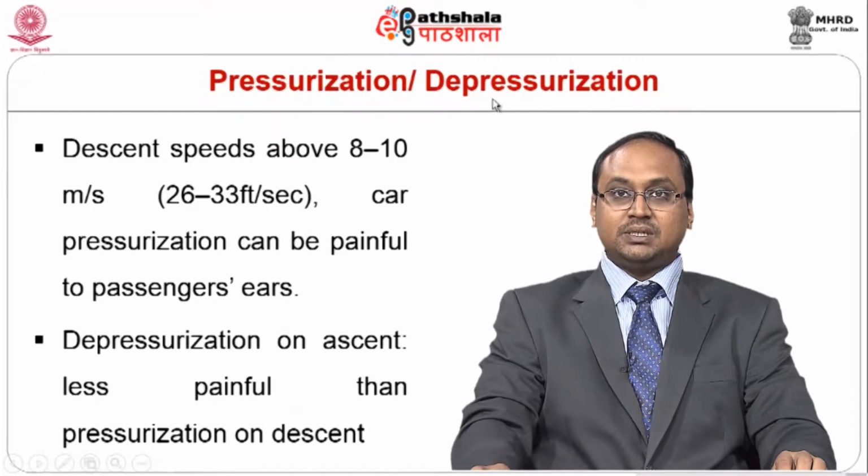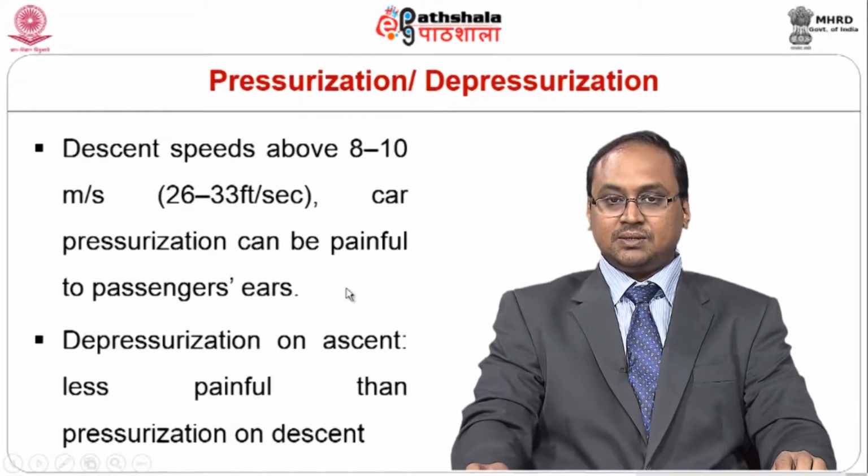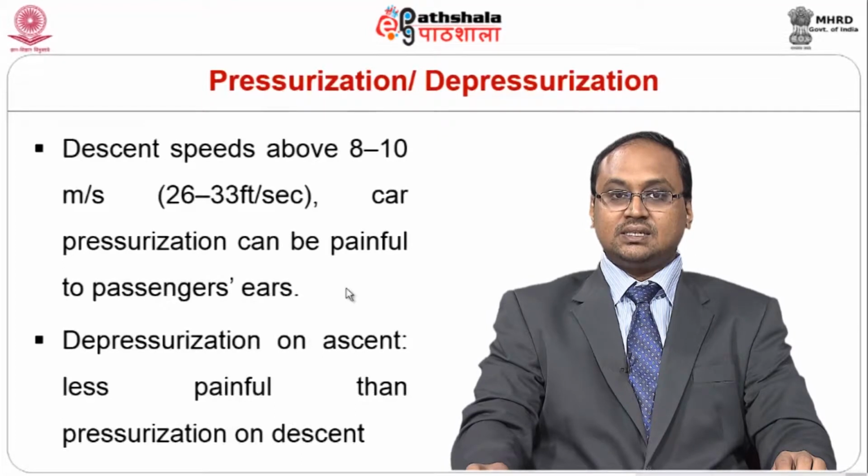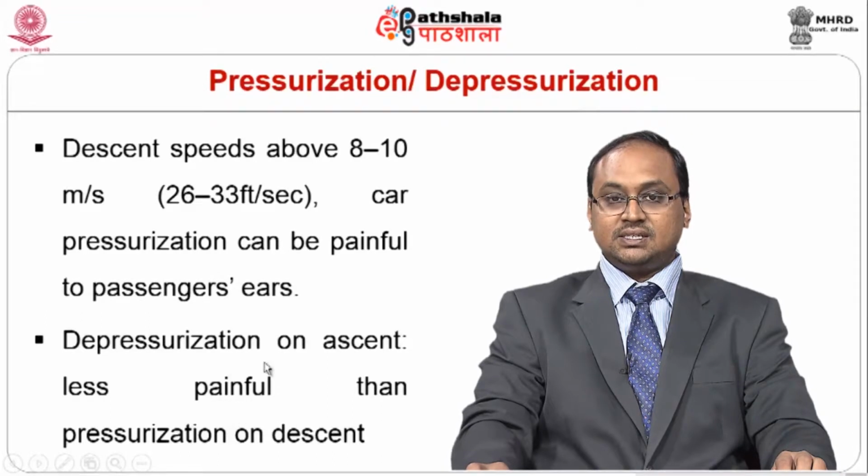Pressurization and depressurization. At descent speeds above 8 to 10 meters per second, car pressurization can be painful to passengers' ears. To take a similar comparison, when a flight is taking off or landing, a person may feel pain in the ear, and that is exactly because of the pressure difference. Depressurization on ascent is less painful than pressurization on descent. This needs to be understood in principle and put into practice when we are executing the project.